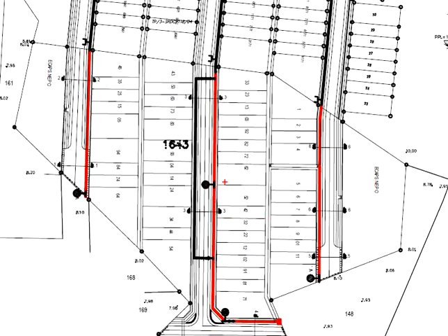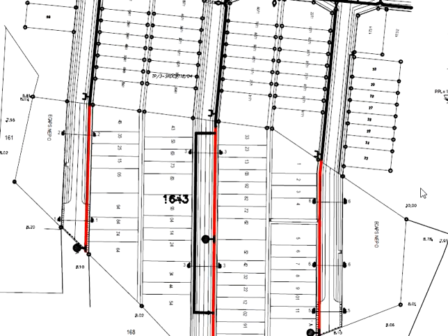And then you will need to plan the locations of the fire hydrants to have a clear distance of maximum 90 meters between one and another. This is for the access of the firefighters. This provides an overview and basic concept of the water reticulation system.